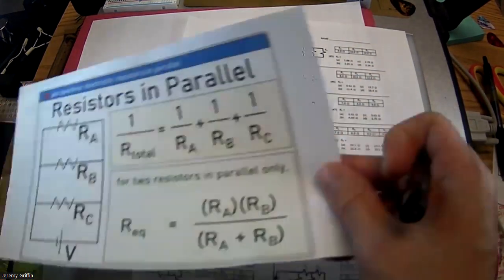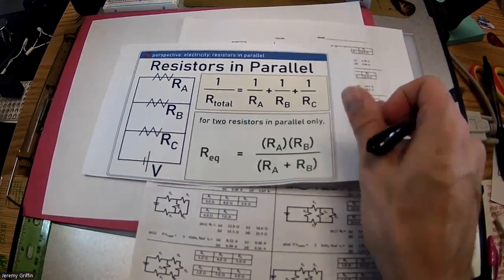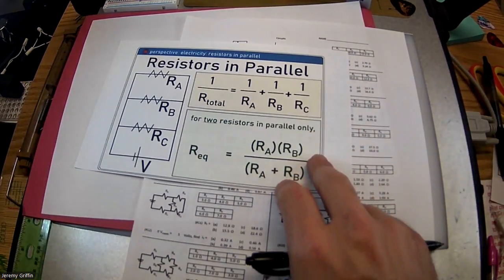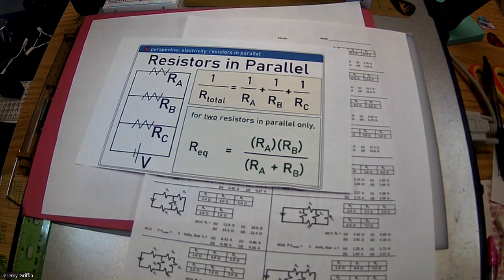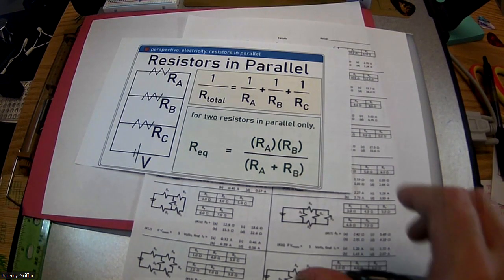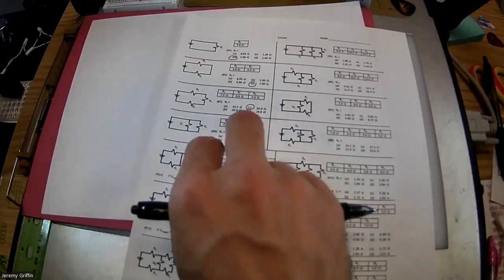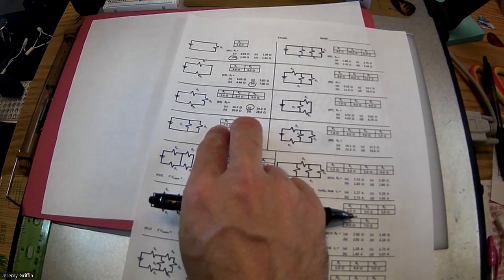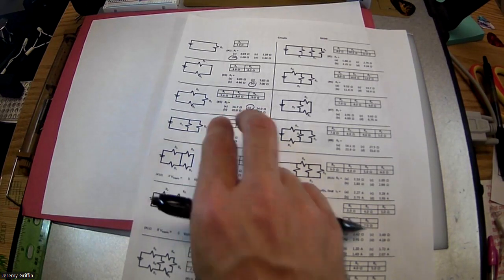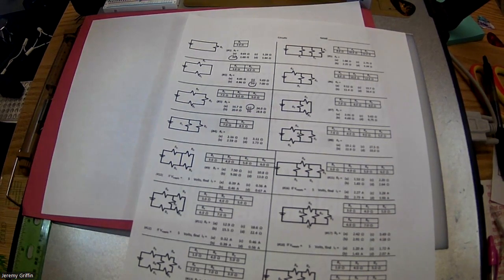Okay? And here's your rule, right? Isn't this like 2 guys painting a fence? Now remember, every team member that you add on painting a fence decreases the total time to paint the fence, right? Or in our case with the electric circuits, every resistor you add on in parallel is going to decrease the total resistance from the point of view of the battery. So my individual resistors are 7 ohms and 8 ohms. Okay, so I'm going to guess that the equivalent resistance is somewhere between 3 and 4 ohms. Wouldn't that have to be the case? It actually has to drop.